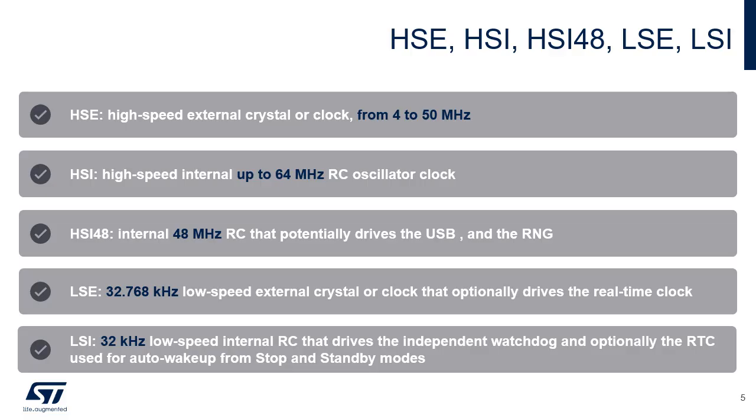The high-speed internal oscillator is a 64 MHz RC oscillator, which provides fast wake-up times. The HSI is trimmed during production testing and can also be user-trimmed to take into account temperature and voltage variations. The HSI can be automatically awoken when exiting any stop mode in order to make it available for peripherals when it's not used as the system clock. The HSI is used as system clock source after startup from reset, configured at 32 MHz.